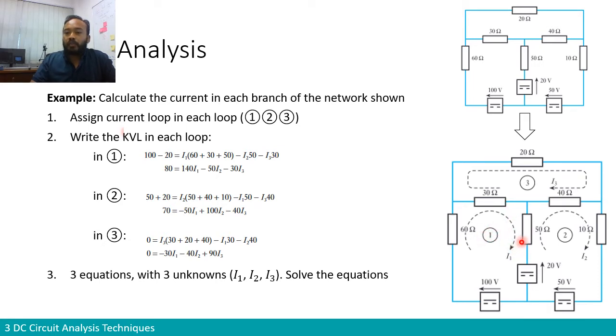And then at the bottom of here, of course, we have also a voltage supply. We have 3 voltage supplies, just now I said 2. So the third voltage supply has 20 volt on it, in the opposite direction of the 100 volt. So if we write the KVL, we see the 2 voltage supplies, 100 minus 20, equals all the voltage inside the resistors. Why do we write it on the other side? Because the voltage is opposing the direction of the voltage of the EMF.